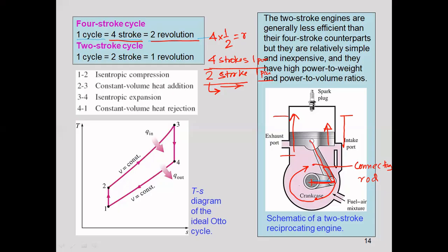The processes are also different. The geometries are different. The constructions are different. In a two-stroke cycle there is no valve, while in a four-stroke engine there are valves, intake valves, exhaust valves, etc. In a two-stroke there are ports. By covering and uncovering of the ports, we get suction, then exhaust, etc. So construction wise, operation wise, geometry wise, and total power wise, there are many differences.